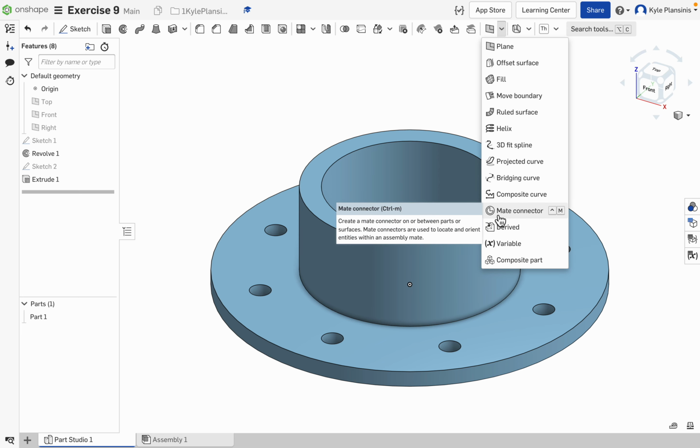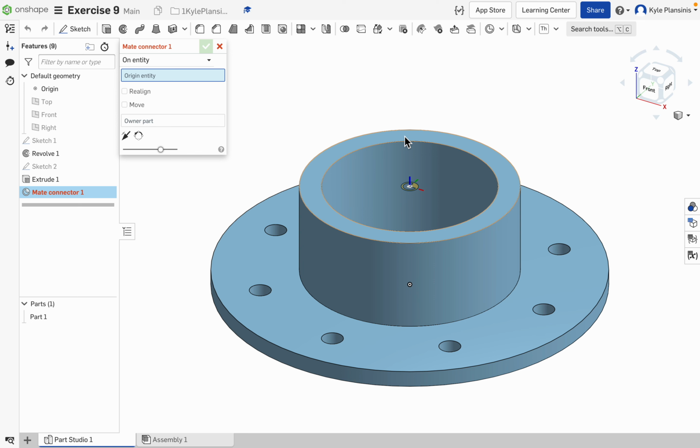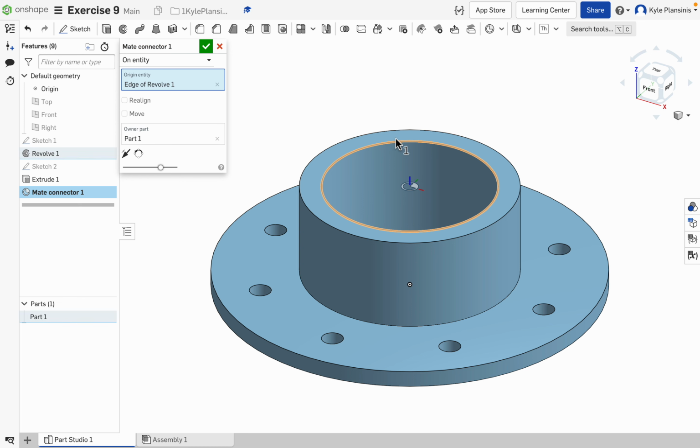So I want this location to have its own X, Y, and Z. You can see our cube has X, Y, and Z. If I go from my origin, that is where X would be this way, Y would be this way, and Z would be up and down. So I want to force another X, Y, and Z in a certain location. I want to hover over the ring of this circle, and it's automatically going to put one of those in the center.